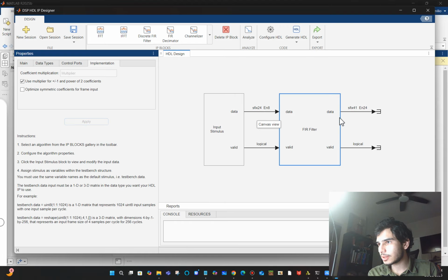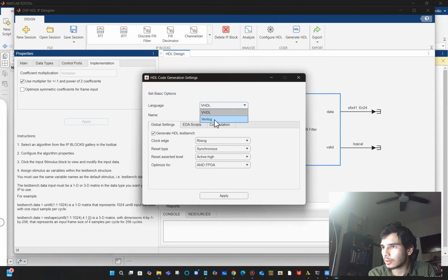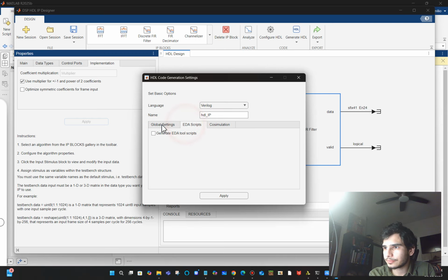So then we get this. And it's good to leave some decimal, so that EN8 means that there are 8 fractional bits. And that's okay, even though we're not going to use any, because the filter does its math in fractional bits, so it's just better to have some. Anyway, once we do that, here, don't need to do any of these.